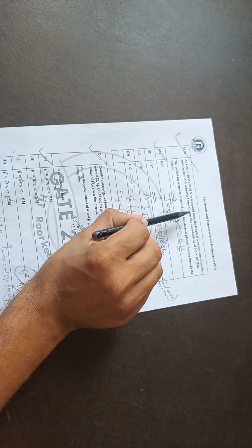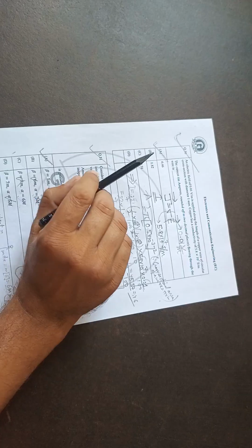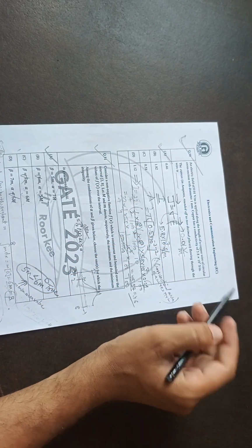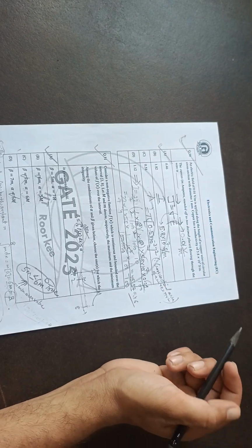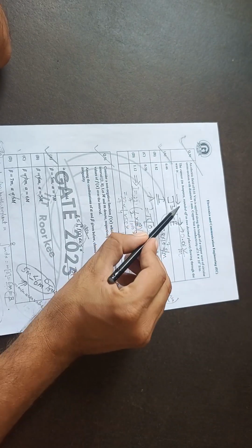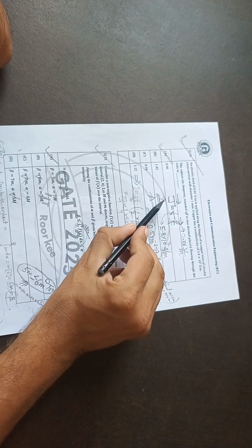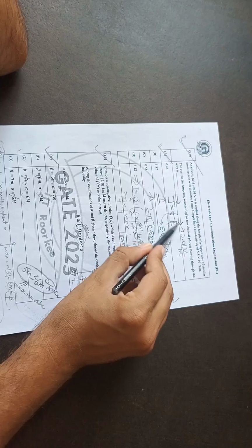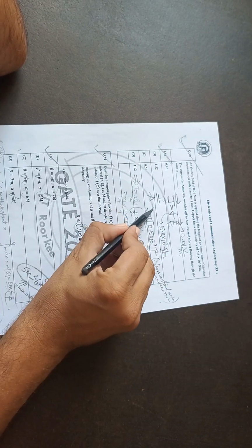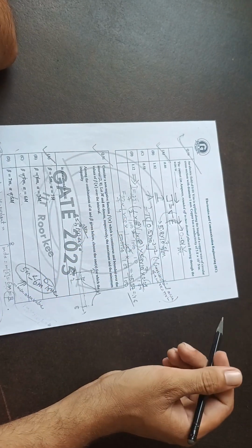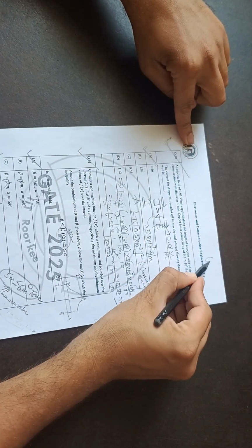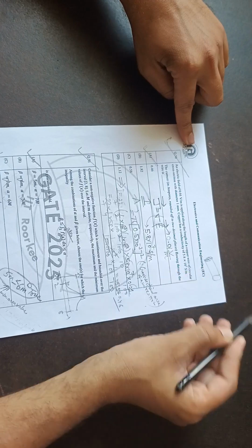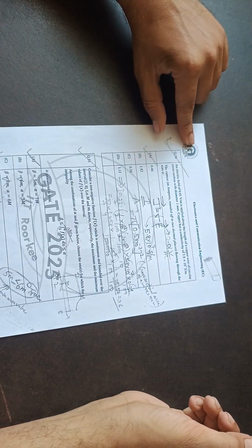An electric field is applied along the length of a copper wire of circular cross section with diameter 1 mm. Copper conductivity is given, and we need to find the current flowing through the wire. Current density is sigma times E, and current density is current per unit area. Conductivity is given, electric field is given, and the area is pi r square, the cross sectional area of the wire, because it is a circular wire.